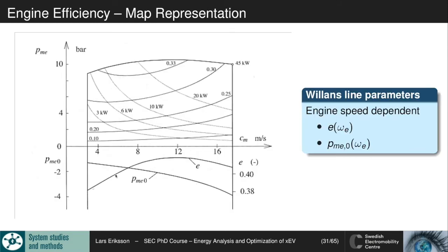And this comes from the book, where they are showing that they have seen the maximum slope has been in the mid-range, while the friction losses are higher at higher speeds. So we have a decrease here in terms of the efficiency. So the trends in between these and the scaling with the engine speed will give us the best operating points that are up here.